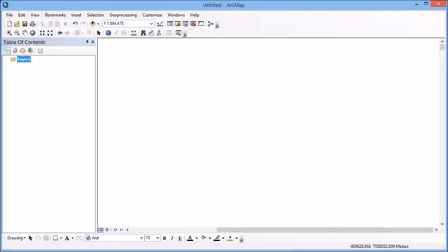In this example, I've got two data sets. One particular data set has coordinates attached to it and the other doesn't. And what I want to be able to do is to compare the two. So to be able to do that, I need to make sure that I get the same coordinates into my image that doesn't have any in the first place. And this process is called georeferencing.